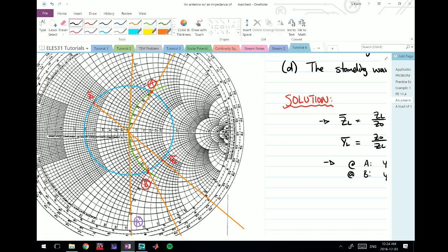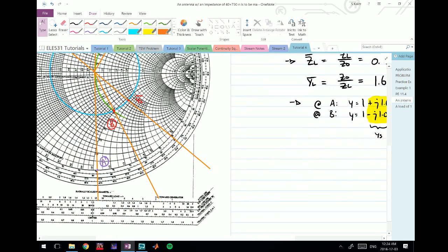But sometimes what happens is, the circuit might call for something a little abstract, so you might need to go further away because closer to the actual interface there might be something else going on. So another thing to note is that we start from here. Whenever we're going for the load, or from the load, I should say, we consider YL, because if you remember, we're talking about admittances in this because it's in parallel. So we start from YL. So this is our starting point for any distance from the load.